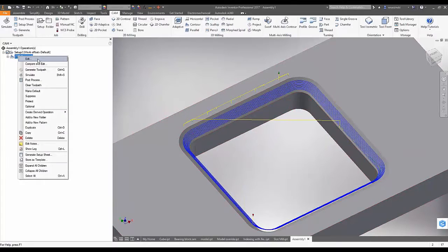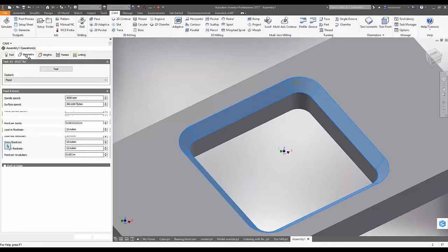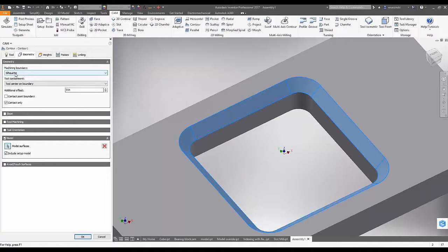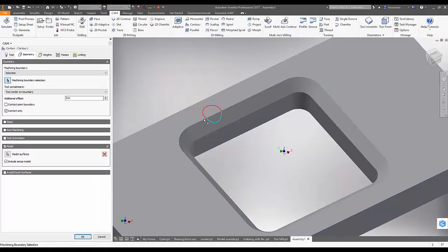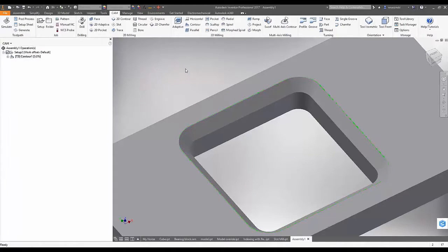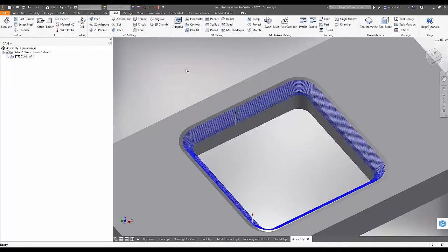So what's happening here, and I can explain why, is this is an override and it adds new to it. Well, it's because you still have your initial model selected, so you need to not include the initial setup model. And the other thing that's interesting here is because you selected surfaces, that's showing it is an override and it ignores everything else that's not selected. So if you unselect use a setup model, then the only thing driving it is these new model override surfaces. Great point. Yep. So now we're only machining that portion.